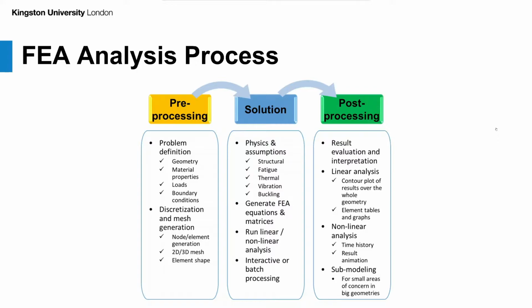And then once we define everything in the pre-processing, we take it to the next stage, which is the solution stage. Within the solution stage, we'll start by doing the different analyses, such as structural analysis, fatigue, thermal, vibration, buckling, and so on. Based on those physics and assumptions that we have, we generate the FE equations and the matrices. And then we do the linear and non-linear analyses, and of course we do the processing on that side. Once we analyze it, we get the results, which are important.